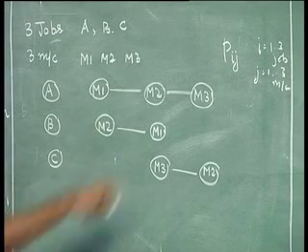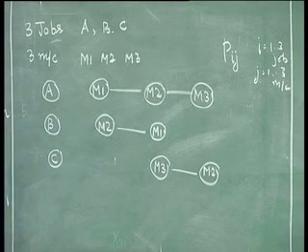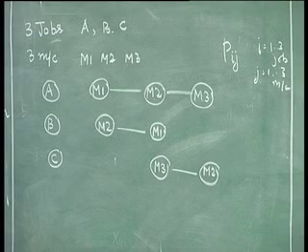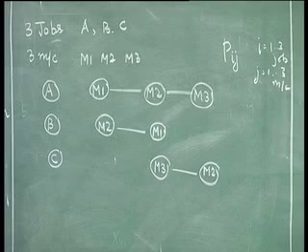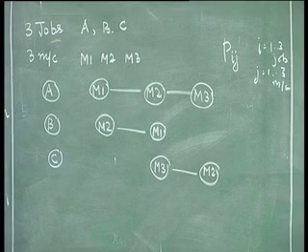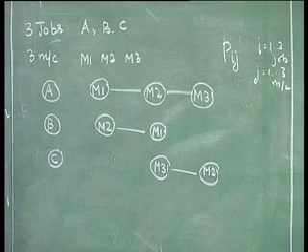This is called a job shop because the order of visit is different for different jobs. If for example, we say that all the jobs will first visit M1 and then M2 and then M3, then it becomes something called a flow shop, where all the jobs have the same order of visit. Now, if the route or order of visit is different for different jobs, then it comes under a general job shop scheduling problem.